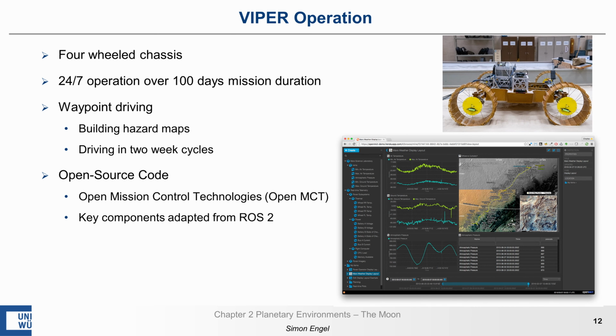You have probably seen that the Viper rover will have a 4-wheeled chassis for driving on the moon. As explained previously, the moon's soil is inherently dusty and a wheeled vehicle could easily get stuck in these conditions. For that, the Viper rover has its 4 wheels mounted on articulated legs that can help to get the rover unstuck and allow several alternative driving techniques besides normal driving.